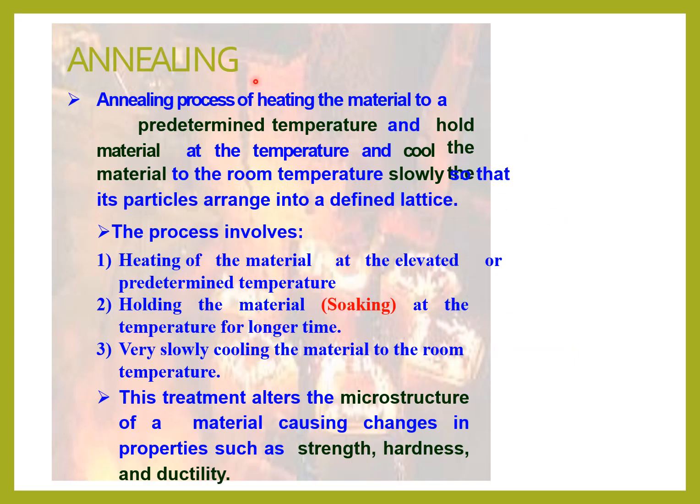So first we will see what is meant by annealing. Annealing is a process of heating the material to a temperature, holding at that particular temperature for some time, and slowly cooling to room temperature. Because of this heating, holding time and slow cooling, the microstructure of the material changes.